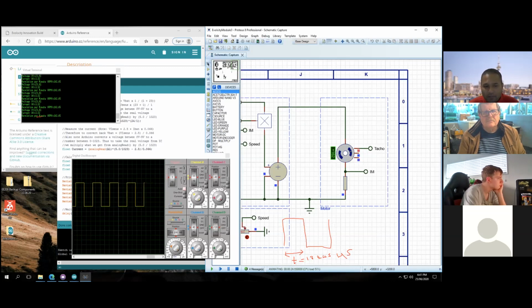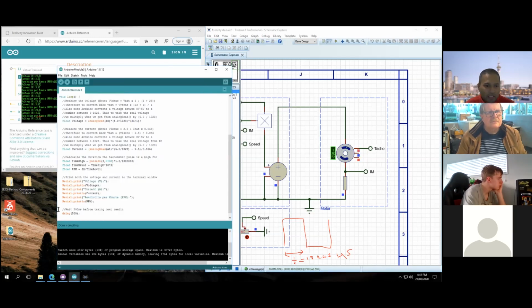Now, if you had the rest, calculating speed, it'll be different for every single cart, right? Because you have a different radius of the wheel, different mechanism, different number of pulses you're getting. So based on your design, you follow these simple steps to work out the RPM of the motor. Like in a normal car, it shows the RPM as well, right? Have you seen it? Yeah. On the dashboard. So you can show the RPM, and after that you use this RPM and the parameters of the slots, number of slots, the wheel radius, and all these things to work out the speed. Okay?